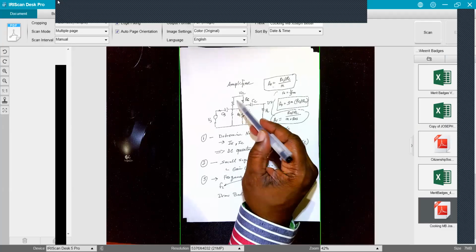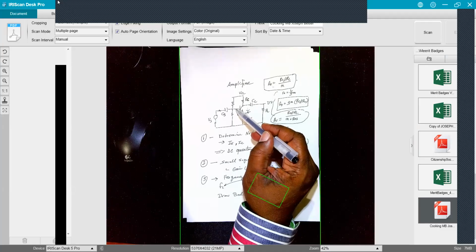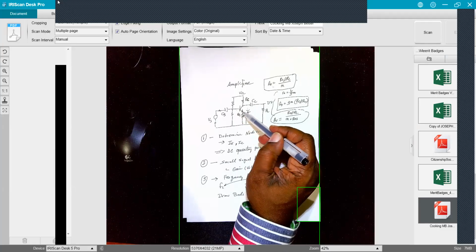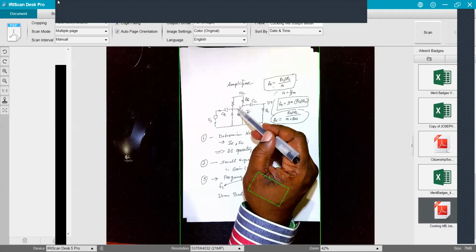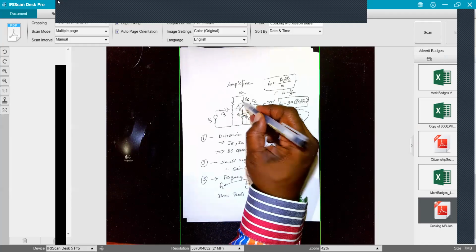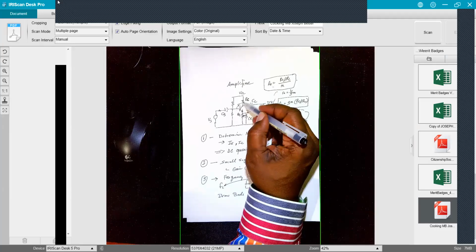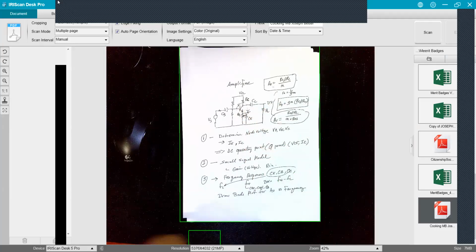So say for example, for one example in class, this was 2.66 volts, this was like 1.89 volts, and this was like 9 volts. Well, 9 volts is greater than 2.66, so this diode here, which we never draw, but sometimes it's good to know, this junction is greater than this, so this diode is actually off. So you're in the active region of operation. Right?